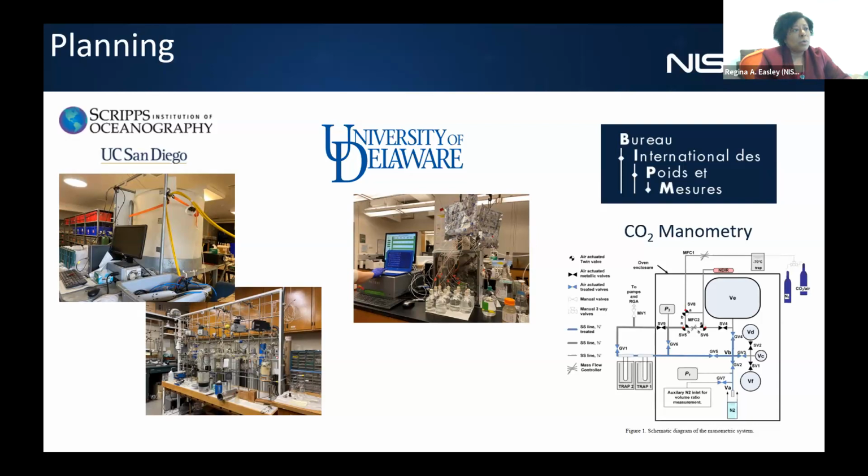And so right now we're deciding our approach, and we have come to the conclusion that in order to quantify the CO2 that's coming off of the vacuum extraction system, we will likely start our measurements using gas chromatography with flame ionization detection with methanation of the CO2.